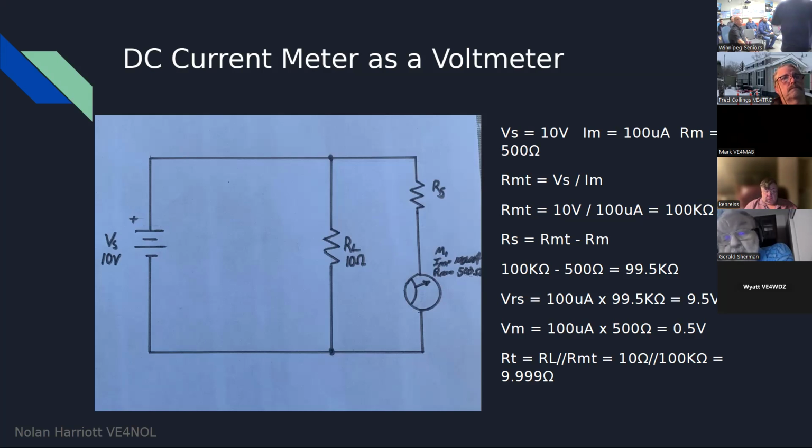Making sense? Is that in addition to what the shunt resistor does? Well, in a shunt resistor, it's going to change the resistance because it's a series resistor, so it is going to add to the total resistance. Now, if your shunt resistor is 0.05 ohms, that's what you're increasing the resistance of your circuit by. So if you're measuring current flowing through a load that's maybe 10K ohms, that's not going to be a huge difference because now you're at 10.05K. But the meter itself, it doesn't add to the shunt resistor? Yes, sure, they work together. It's a combination circuit, right?